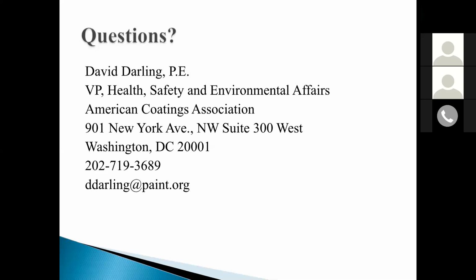Right. Good question. You definitely got into the complexity of it real quick here. Many of these product data sheets, depending upon whether the coating is going to be thinned or not, I would think many manufacturers would give the instructions to the applicator as far as how the coating is to be applied, what type of solvent is to be used, and what ratios, to still be in compliance.